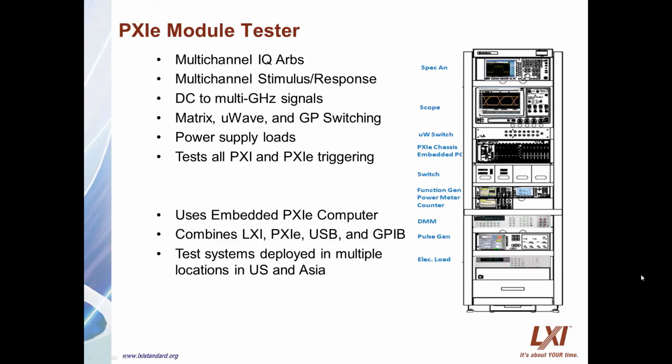The test system utilizes an embedded computer in the PXIe mainframe, which controls all the instrumentation in addition to controlling the PXIe modules using IVI drivers and sometimes direct control using the SCPI language. Each LXI device connects to a multi-port LAN switch, which then connects to one of two LAN ports on the embedded computer.